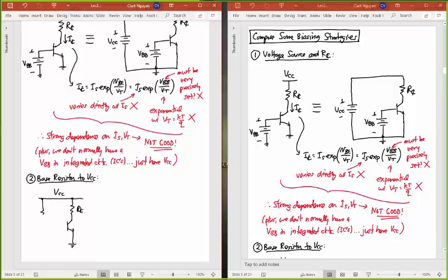And now here, I'm going to use a resistor RB to establish my base current, IB, into my transistor and to generate the needed VBE voltage across this to get my goal, which is a very specific RC.